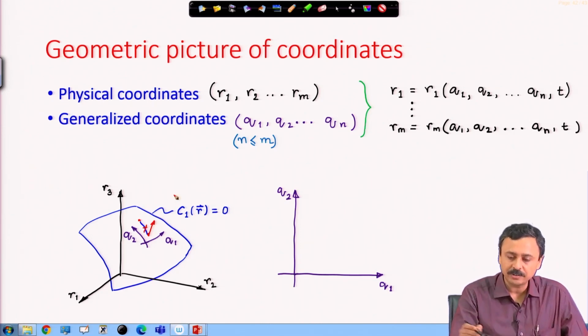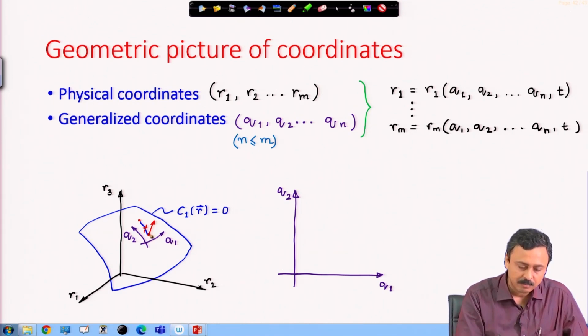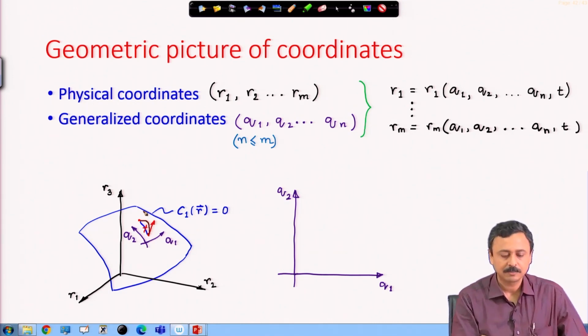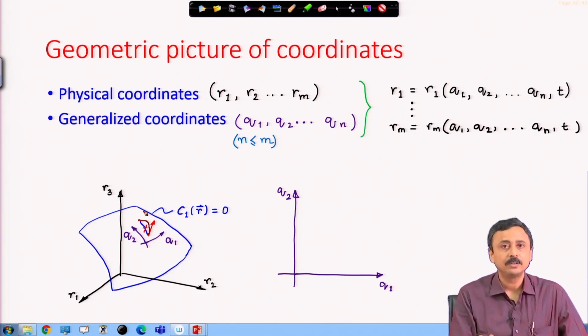But since you can move in that red arrow direction, you can move possibly like this. You can go to any configuration. That is not restricted by a non-holonomic constraint. At a point there can be local directions in which you can move, and if you can judiciously change your directions as you move, then you can relocate to any other point. There is no restriction on where you can relocate.